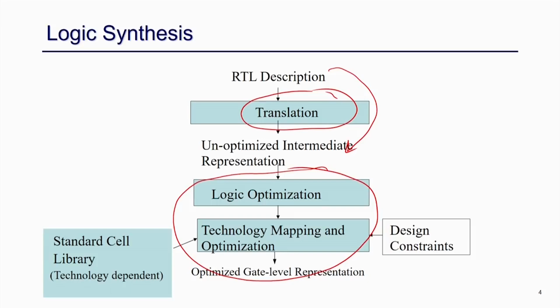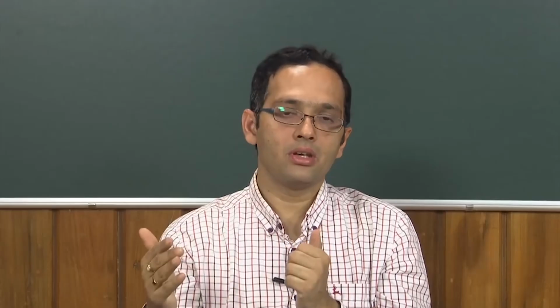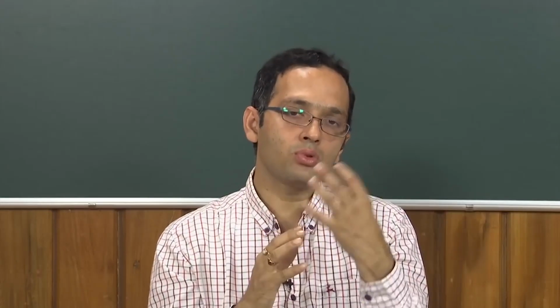Then we try to do all this optimization without looking into the actual technology dependency, that is, your target architecture. Your target architecture may be, say, FPGA or ASIC, and we are not going to consider those technology dependent things in the technology independent step. But in technology dependence, for example, in an FPGA, we have LUTs, DSPs, and block RAMs. So when you are talking about mapping or optimization, we try to map those AND gates and OR gates to those LUTs, because those are the technology units of that particular FPGA.